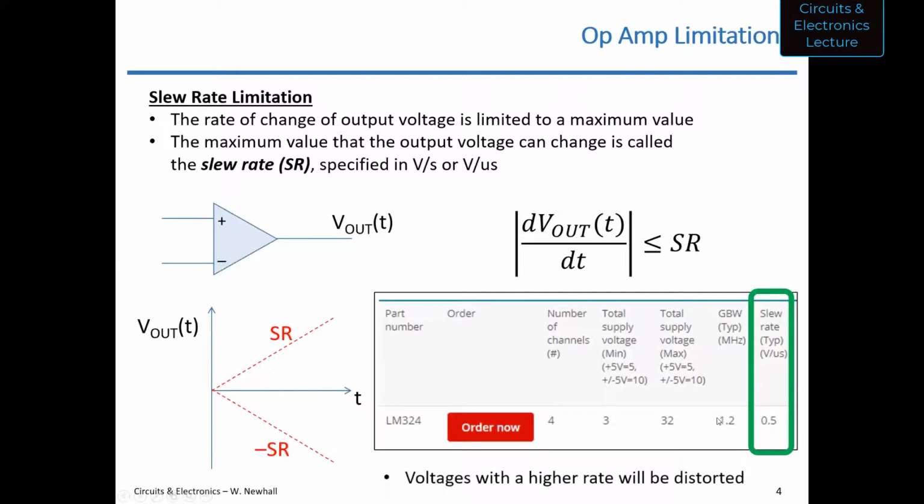Professor? Okay. Yeah. So is V out always time dependent? Because I thought from what we've seen that it was constant. Right. So, well, imagine that inverting amplifier. I drew a sine wave for the output. So if you have, let's say, an inverting amplifier that multiplies the input voltage by 10, I could have a 1 volt sine wave amplitude at the input, and that would be a 10 volt sinusoidal output. Does that make sense? Can you say that again?